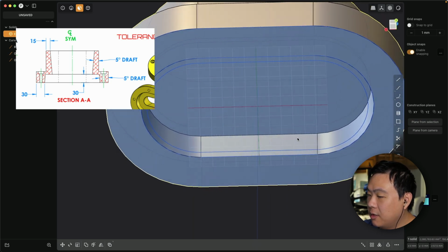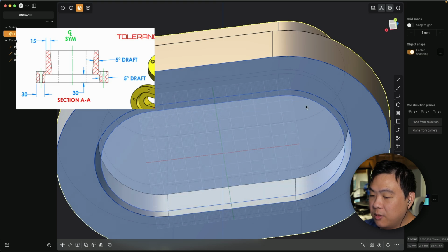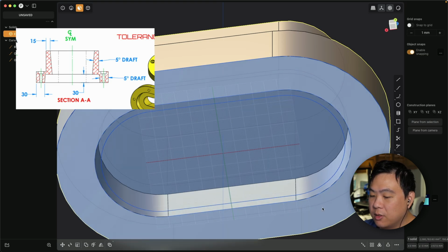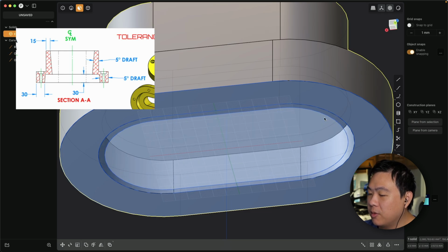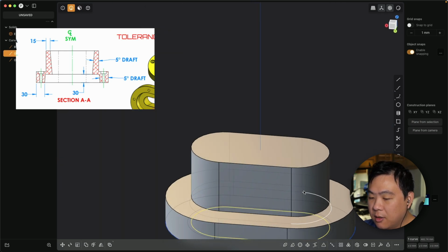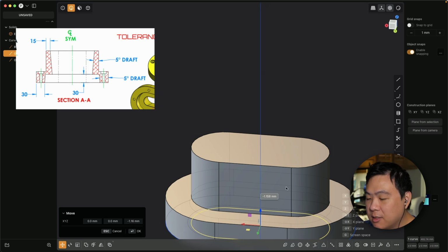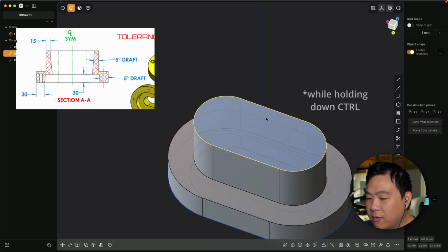And similarly, let's do that now from the top. The easiest way to do that is that this inner oval is what we use to define the extrude all the way to the top. So to start the extrude from the top, I'm just gonna take this curve that we have already. I'm gonna press G to activate the move tool, Z to lock into the Z axis, and then just lock it all the way onto this top face. So we can start off from the top.